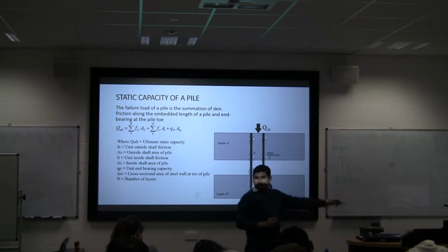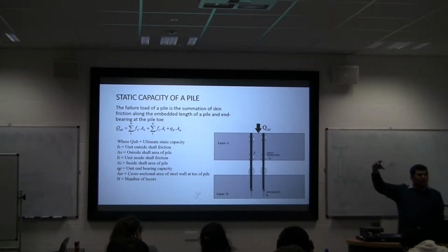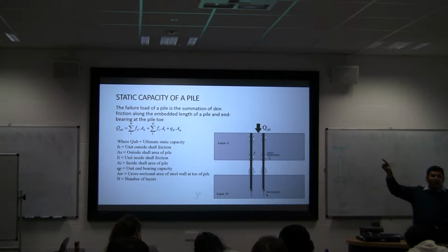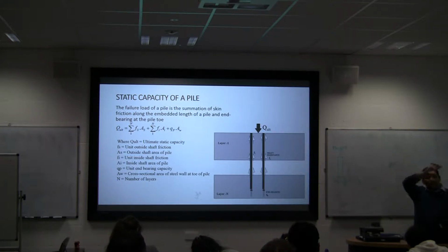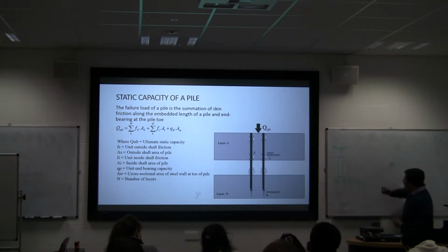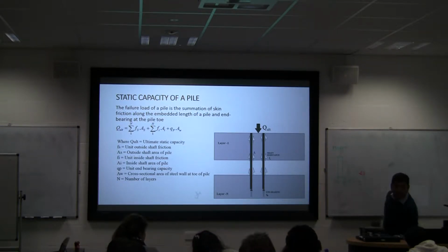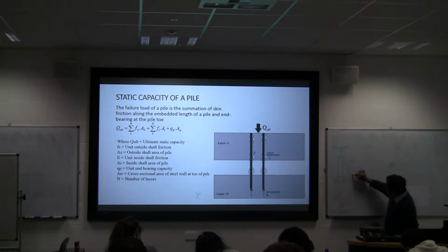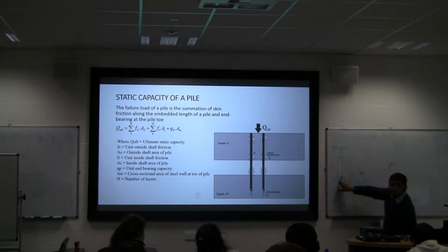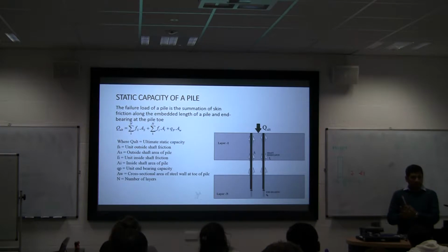You put down there, right? And end bearing resistance is something quite like bearing capacity, like cNc, half gamma N gamma, gamma D Nq, those terms. This is there, right? So this will have a unit of kilonewton per meter squared, kPa, and times meter squared, you will get this as a force. Okay? It's a plugged case, so the bottom is plugged.